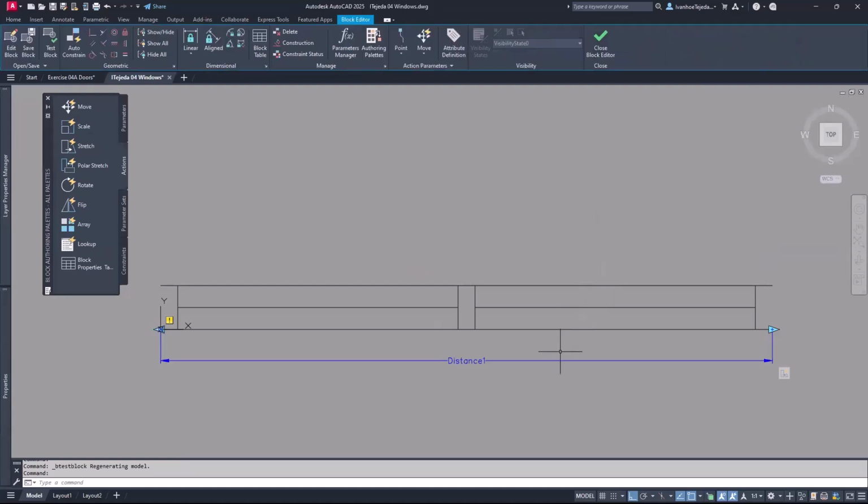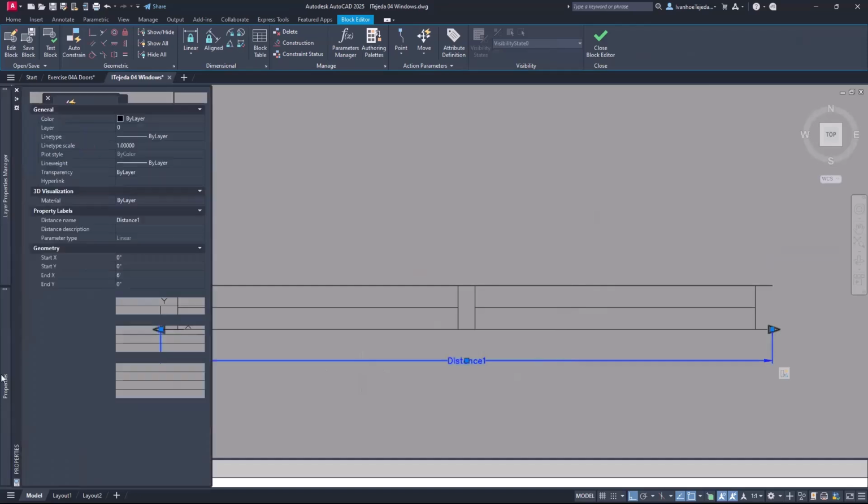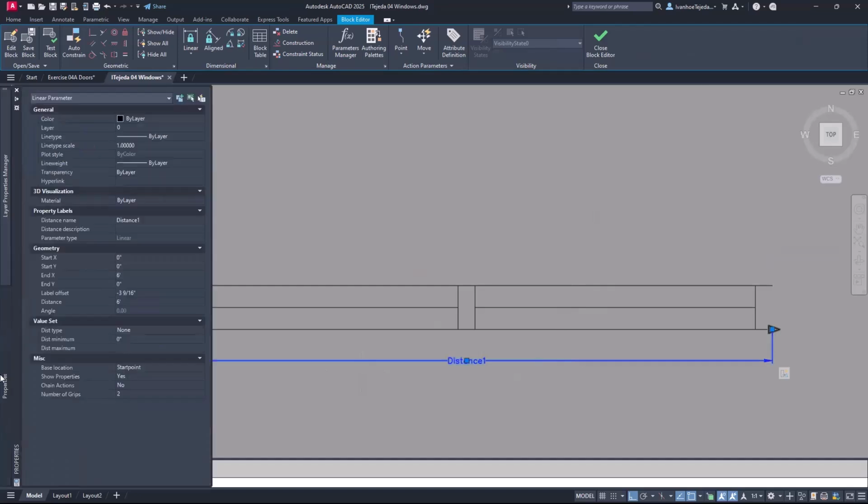And let's see, from here, can I actually pick the distance and then go to the properties? Yes, I have to. So the distance type has to be increment. Distance increment, I want to go for inches. Distance minimum. So the distance minimum here, I guess if I have a single window that's 2 feet wide, I could go 4 feet on this because it's a double, so I'll go 4 feet. And then the maximum distance, I don't want this to be any wider than, let's say, 8 feet. And these are personal choices. You can set it to anything that you want, and then I'll enter.